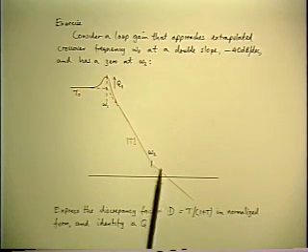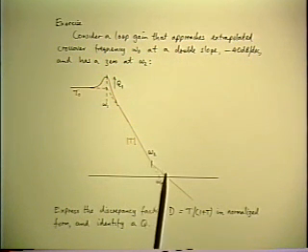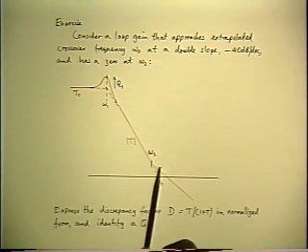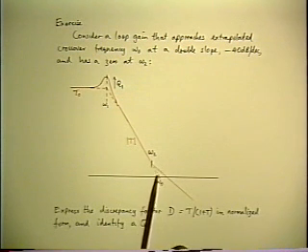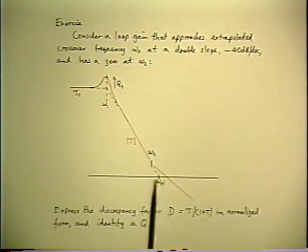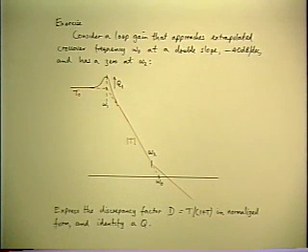Because small or even large changes of the ESR make correspondingly large changes in the stability margin. So that's violating the second answer to that question. How much margin do you need? It's directly sensitive to an uncontrolled second-order parameter. So that's a horror story, because it's a combination of all of the worst things that you can do. And it's especially ironic, isn't it? Because the second vendor was giving them a better capacitor.